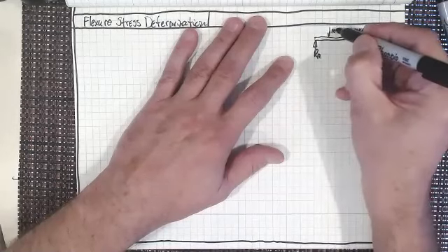Now, in summing, R sub A and R sub B, I think everybody can see are going to be equal in this case. So when we sum the forces, R sub A plus R sub B, they're going to be equal to 30 kilonewtons. And I want to make sure I leave enough room here, because I need a little more room for the other things.